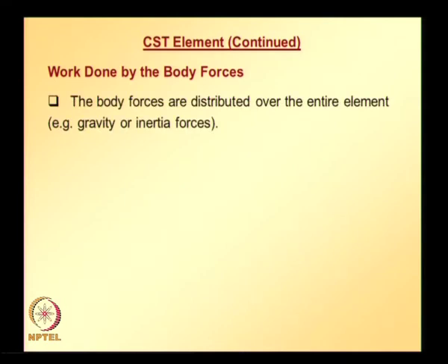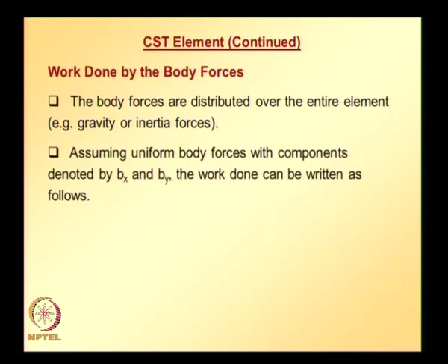For example, gravity and inertial forces. Again, for illustration purpose, let us assume uniform body force with components bx, by. Since we are dealing with two dimensional problems, plane stress, plane strain, we are considering only force components in x and y directions.